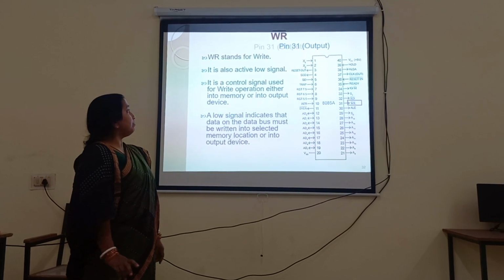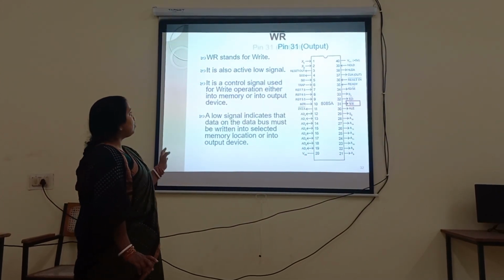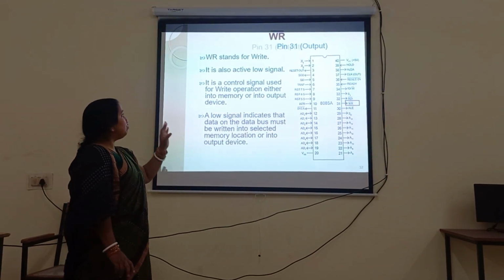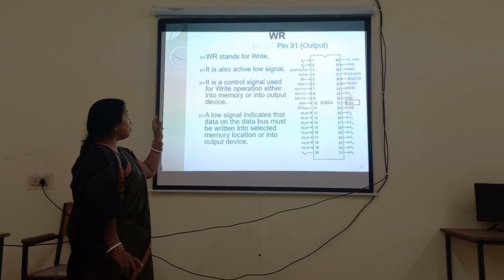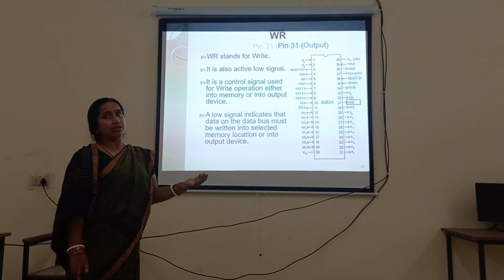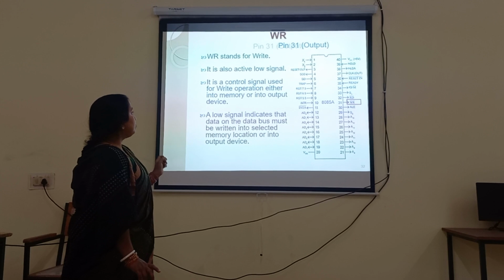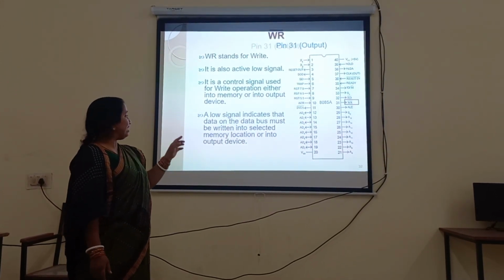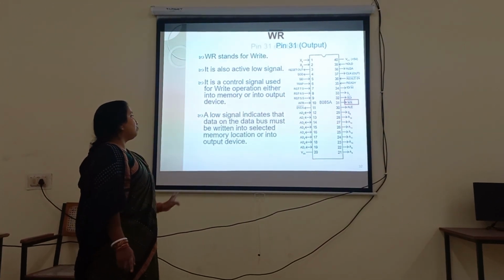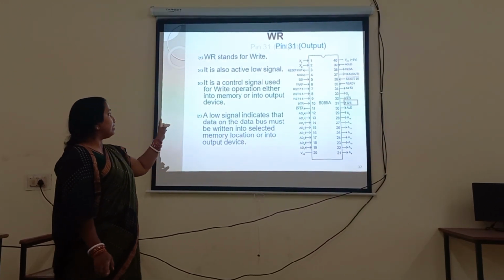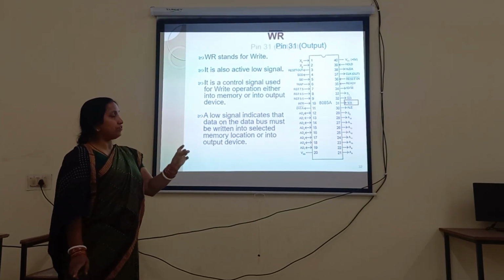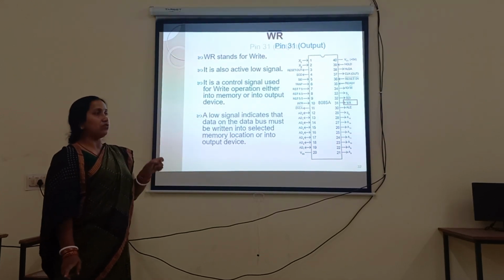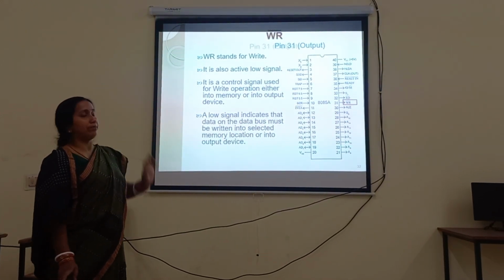So the next one, WR bar. WR bar means a write operation, which is also an active low signal. It is also a control signal used for write operation either to memory or to an input output device. So a low signal indicates that data on the data bus must be written into the selected memory location or into the output device.